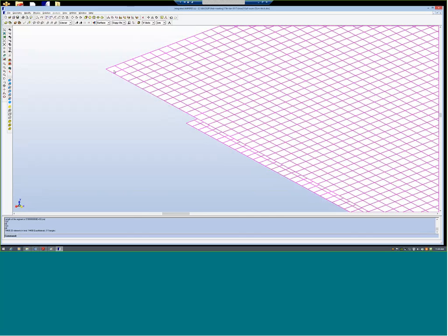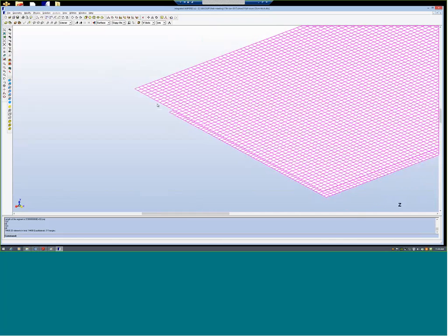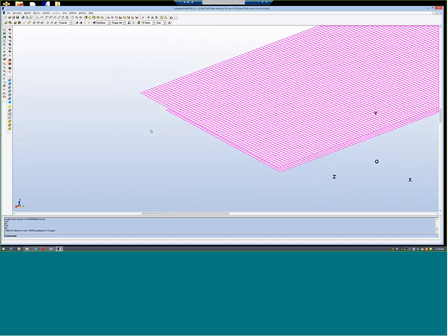But the size, at least, you should have 5 centimeters. And if the thickness is 2 centimeters, so 2 times 5, 10 centimeters. So the element can have a size of 10 centimeters by 10 centimeters. In such a case, a fewer number of divisions is good enough for me. Anyway, that is the way you have to assign the elements.